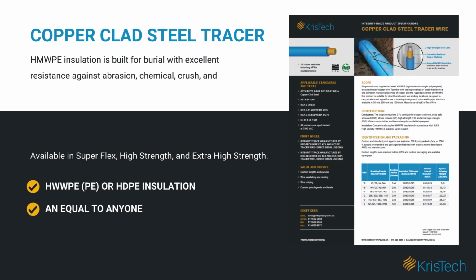Copper does conduct electricity better than copper-clad steel, but in tracer wire applications, this doesn't apply. We are more concerned about the break load when we talk about applications. Copper-clad steel is best for drilling, boring, and pipe burst applications because it's a lot stronger compared to copper.